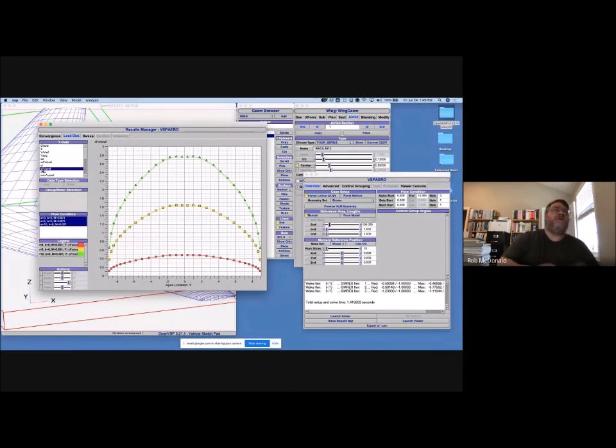Whereas when we talk about the total lift coefficient on an entire wing, it's a capital C and a capital subscript L. So you take the local CL, the local lift coefficient, times the local chord, and then you divide it by the reference chord of the whole thing, and that gives you a shape of what the distributed force is on this wing. And fortuitously, in this case, it looks pretty close to elliptical. But when we talk about an elliptical lift distribution, this is exactly the chart that you want to look at. For low induced drag, you'd like this to be elliptical.